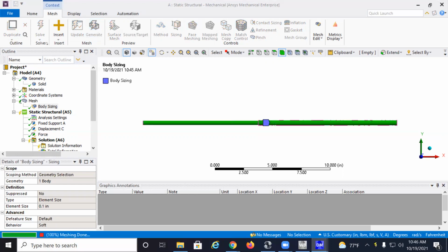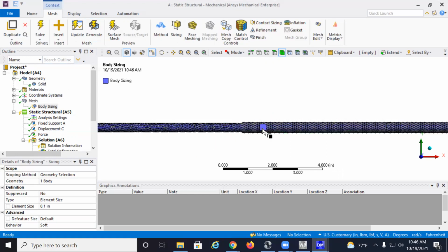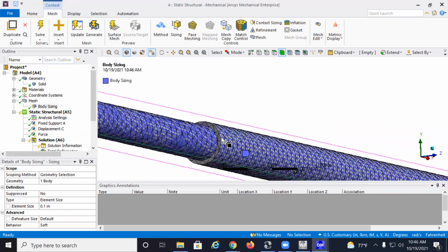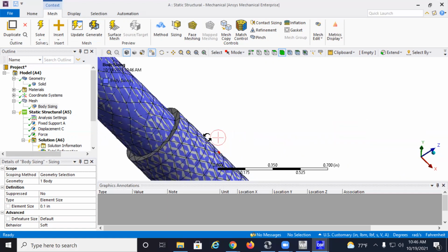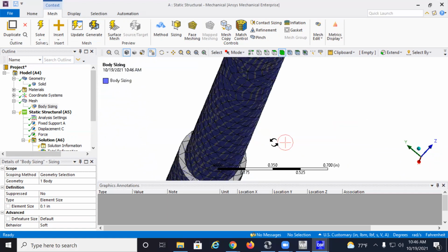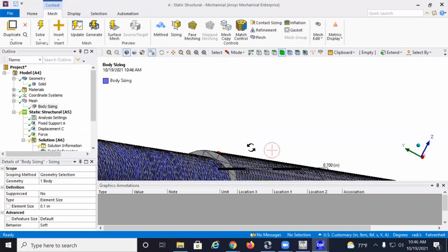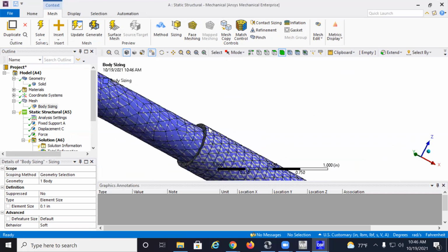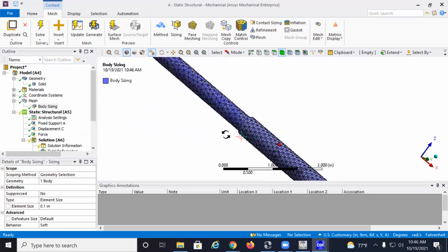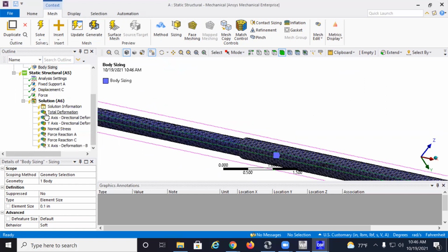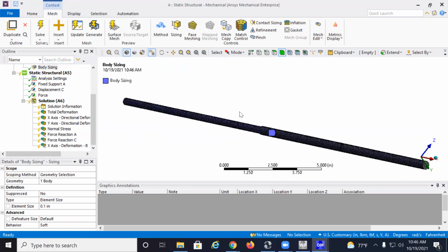And see, ANSYS now is going to take time to create a mesh. But look at this mesh. What do you think of that? You remember all the crooked faces we had? Look at this. Isn't that a much nicer mesh? Okay. Is this going to affect the behavior? Let's check. So I'm going to have to run my solution again. And let's try to keep an eye on how much time this is going to take. So I'm going to select solve.